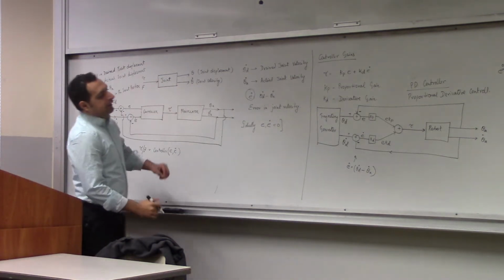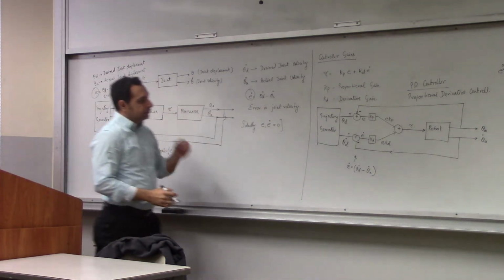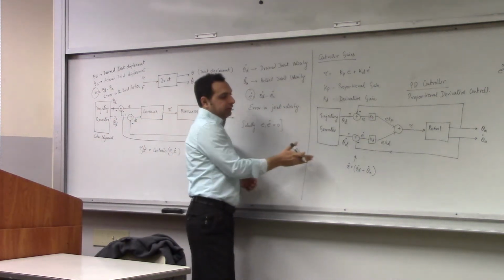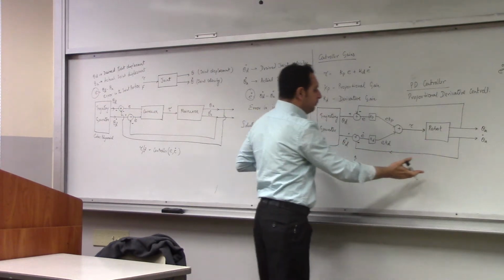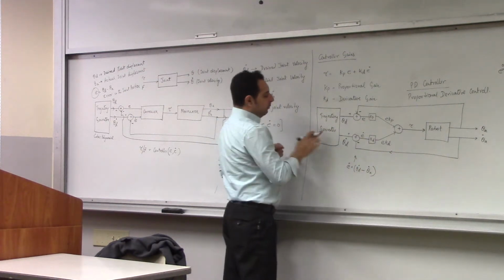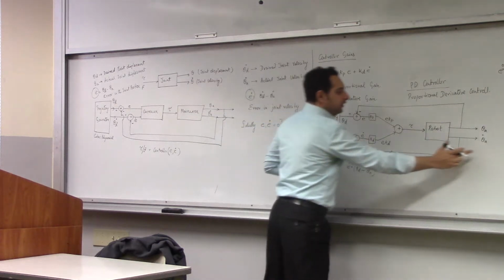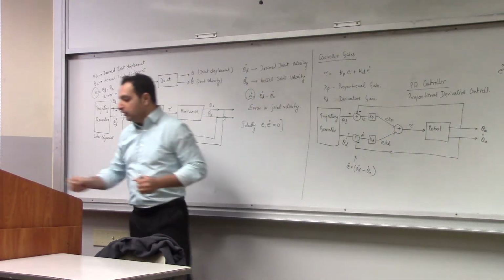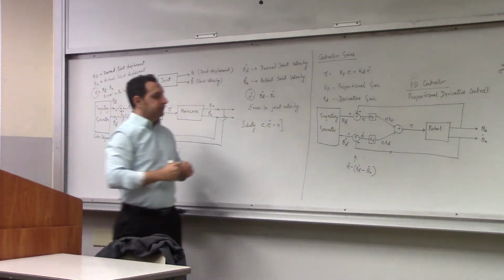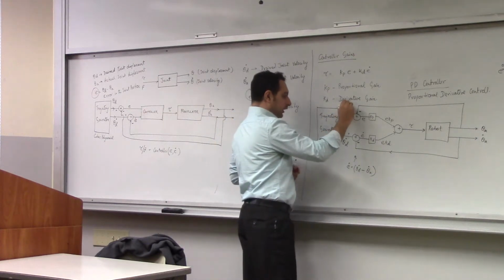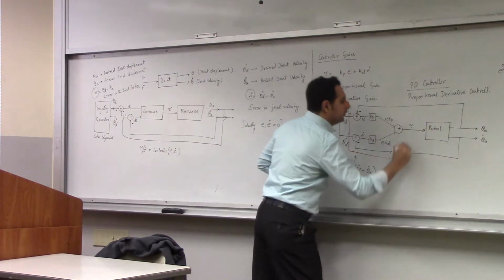Okay, so in this case, everything is in thetas. So this is a trajectory generator. This is happening in joint space, okay? Because here you have thetas, here you have thetas. All of this is your calculation in joint space. This part is your PD controller.